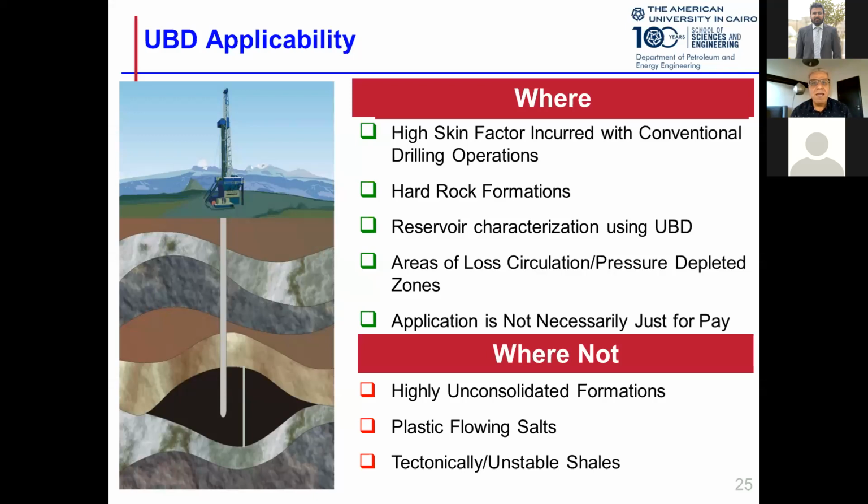The GC unit does analysis from C1 to C6, along with some sour gases. And now we plot different ratios, and when these ratios cross over, they tell us that we are almost 50 or 30 or 40 feet above the reservoir. So we get guidance by the use of technology in order not to miss.